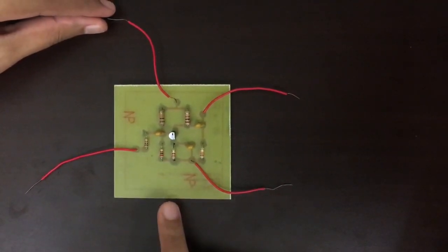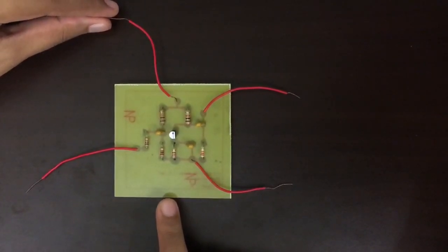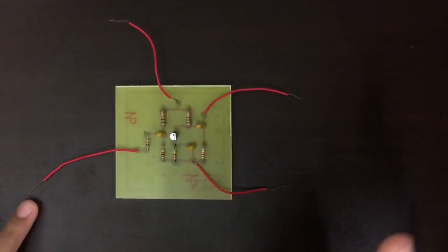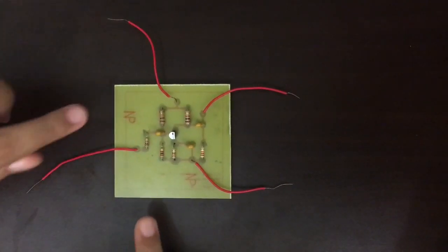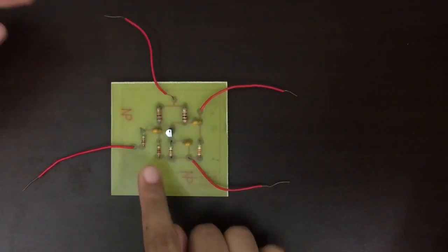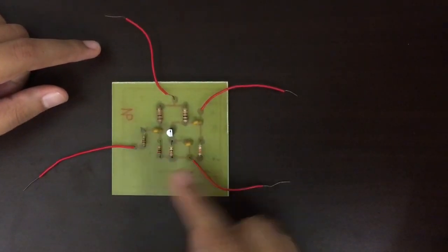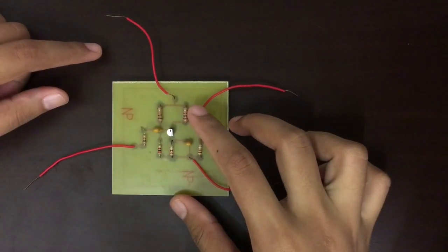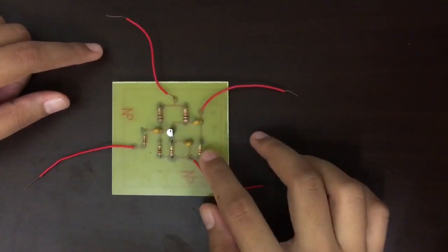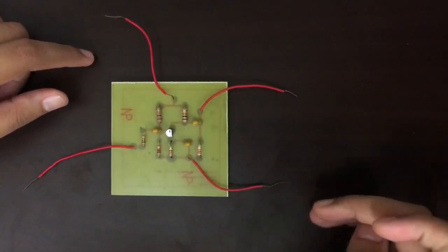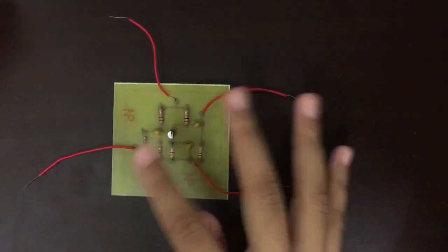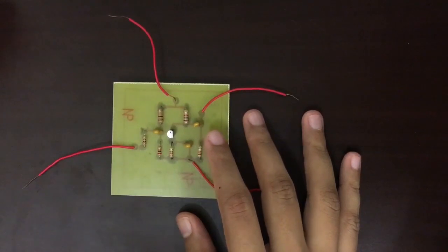For the VCC pin, we set it to 15 volts, Vin 1.5 VRMS with 60 Hz, and we chose RS to be 1 kilo ohm, RB1 10 kilo ohm, RB2 2 kilo ohm, RC 1 kilo ohm, RE 220 ohm, and also RL 22 kilo ohm. For the capacitance value, we chose 3 capacitors with 1 microfarad.